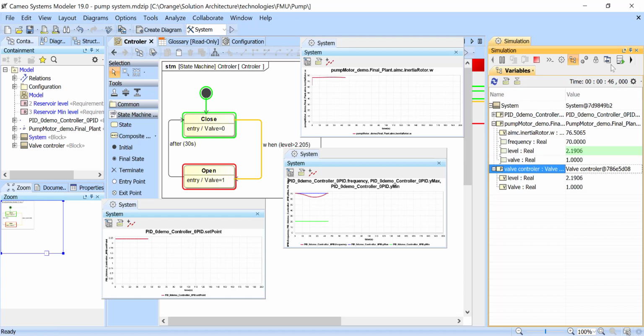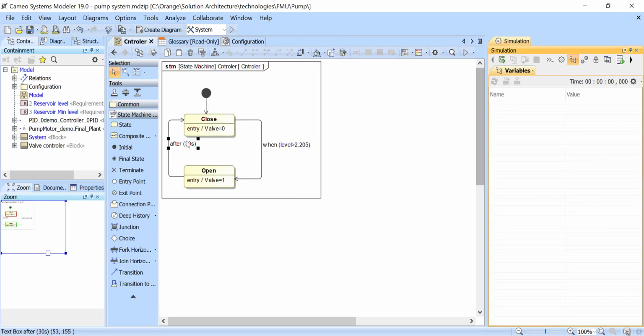We always see the execution clock here, right? And we see that we reach the limit of another requirement because this executed too slowly. So the valve was open too long, right? So maybe we should stop it and switch the duration to 20 seconds, so that the valve would be open only for 20 seconds.